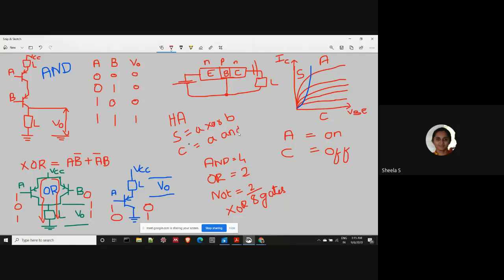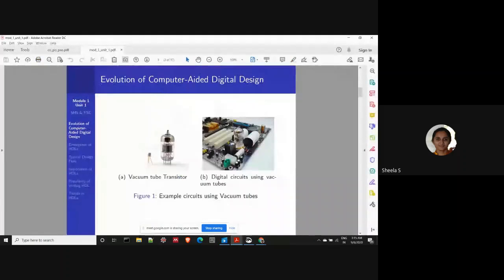So for an AND gate we need two transistors. So totally how many transistors are required for half adder? For XOR gate 8 transistors and for AND gate 2 transistors. Totally 10 transistors are required. And we have to connect those transistors using these types of discrete components.